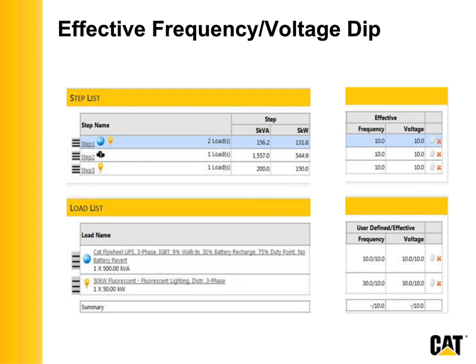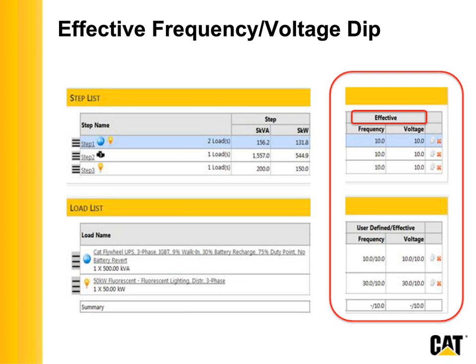Here we're also, I just talked about this. I talked about effective frequency dip and voltage dip. That's the restrictive dip. It's important to understand that a couple of things here are really important about sizing your gen set. I'll talk more about this later, but you don't want to sequence all of your loads into one load step if possible.